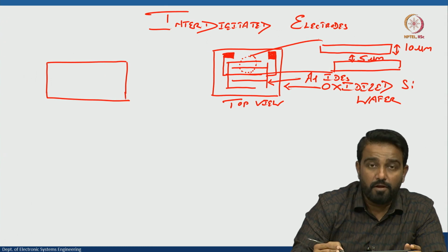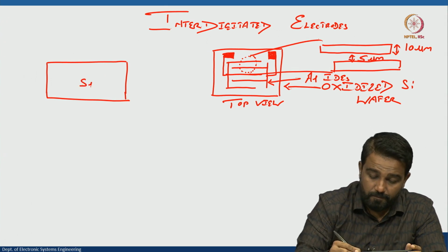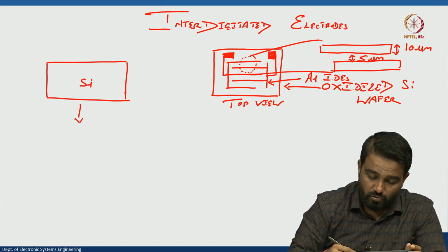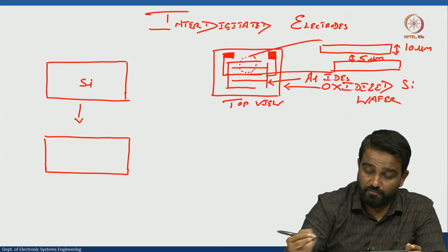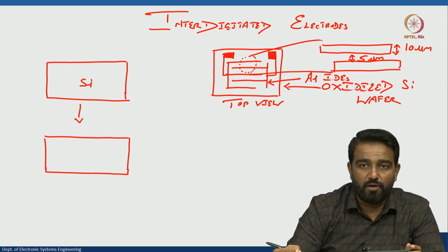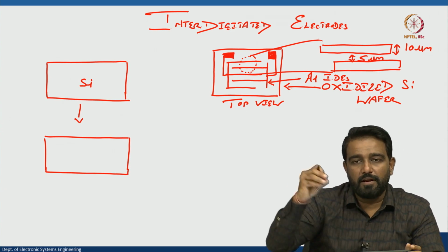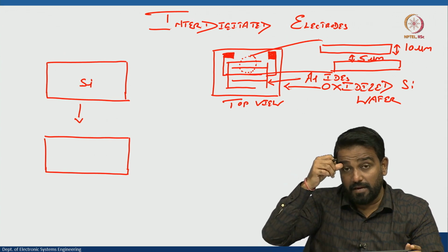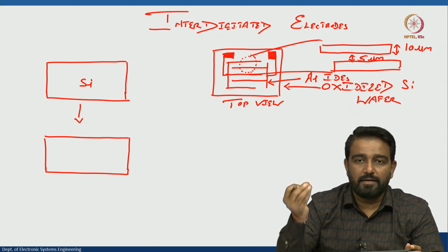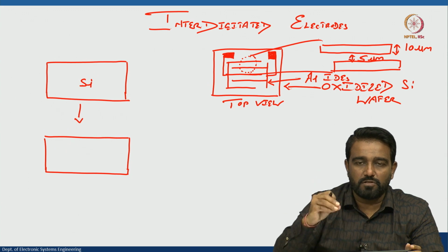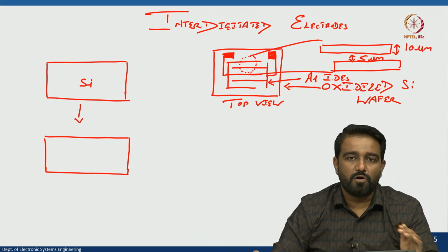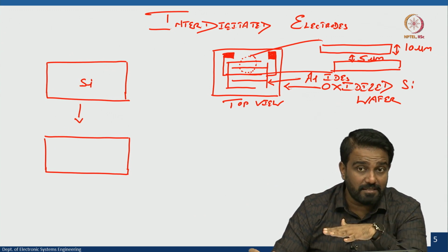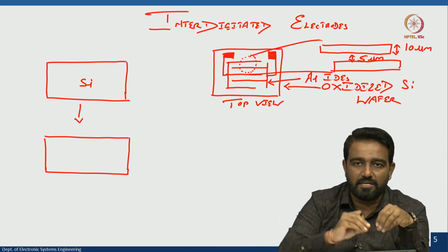So, you have your silicon as a substrate, then you of course do pre-cleaning and you dip this wafer into HF, right. I told you HF. What is HF? HF is hydrofluoric acid. When you dip the wafer in HF for certain seconds, the native oxide, the oxide that is grown onto the silicon because of the presence of oxygen in the atmosphere, can be etched because hydrofluoric acid is the etchant for oxide.